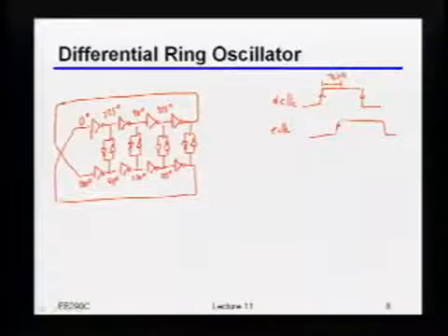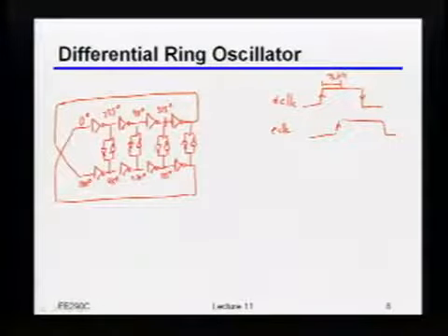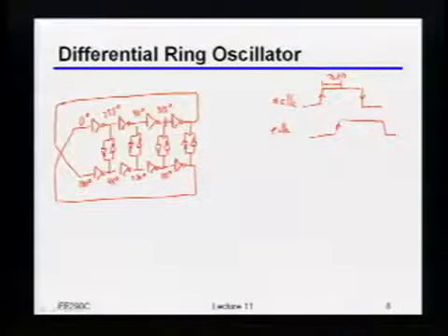As we were implying a second ago, because I want to use both the 0 degree and the 90 degree, and I really want them to be 0 and 90 degrees, I really have to make things match, right? So that means that all of the level shifting, everything that I do on this stage, I better also do here. And typically you better almost always do it here and here also, because if you don't, you're likely to get some mismatch. Okay? So this can indeed be done.